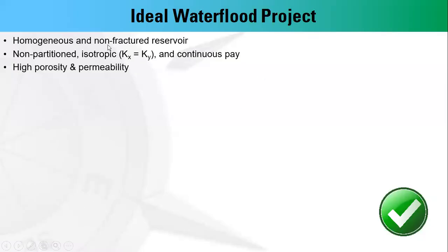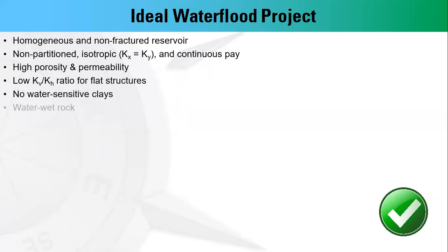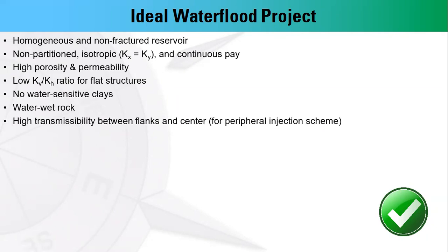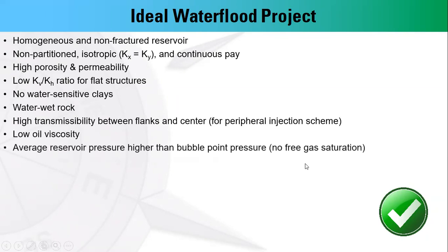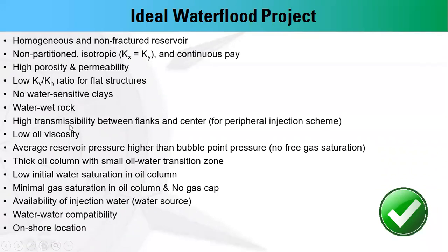Homogeneous reservoir structure, high porosity, high permeability, no water sensitive clays to avoid water compatibility issues. It's preferred for water wet reservoirs, high transmissibility between the flanks of the reservoir in case of peripheral injection, low oil viscosity, low oil density, and so on, thick oil volume. All of these parameters are ideal or recommended for successful water flooding or water injection projects.